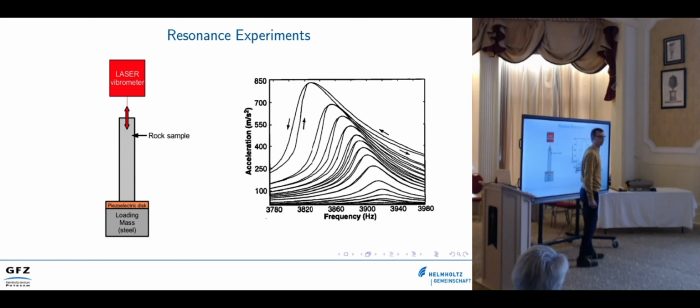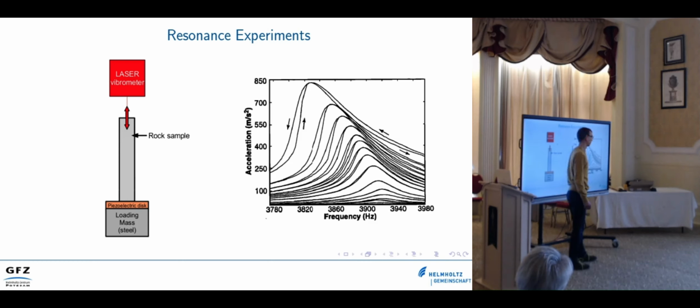Then this is done for different amplitudes of driving, of oscillation, and we see that when we increase the amplitudes, the frequency decreases, so the material gets softer. And there's lots of other phenomena. For example, when you sweep in that direction to increasing frequency, you walk along this path, or when you sweep downwards, you walk along a different path. It's asymmetric, so we have a steeper curve here than on the other side.